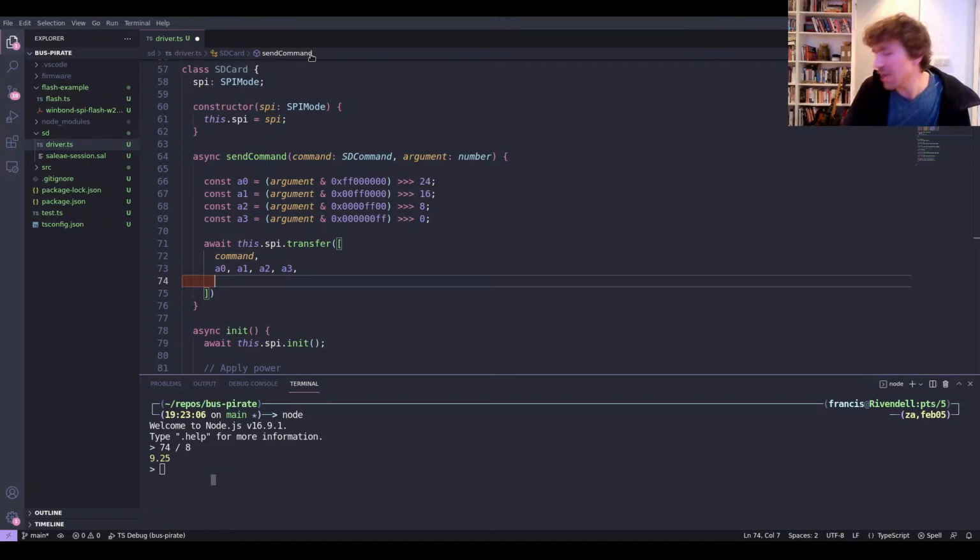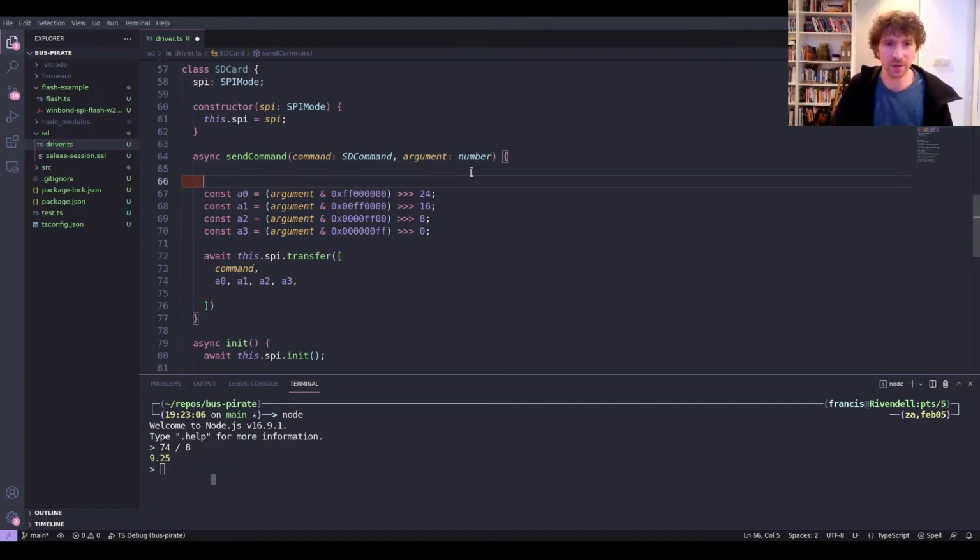But it's a way of checking that your data is valid when you've received it, right? You get some data and you compute the CRC from the data you received and you check they match. And actually CRC has this very cool property that it can give you some information about where errors occurred or how many errors occurred. It's pretty cool. But I'm not going to build all that CRC logic here.